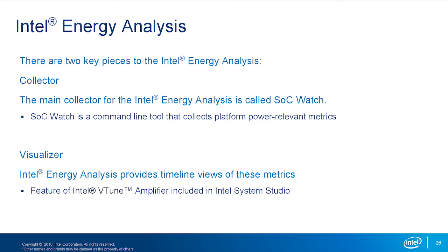So there are two components to the Intel Energy Analysis tool. There is a collector and there is a visualizer. The collector is called SoCWatch. So it's a command line tool that collects platform power relevant metrics. It collects things like C states, P states, ACPI states, and different power events.